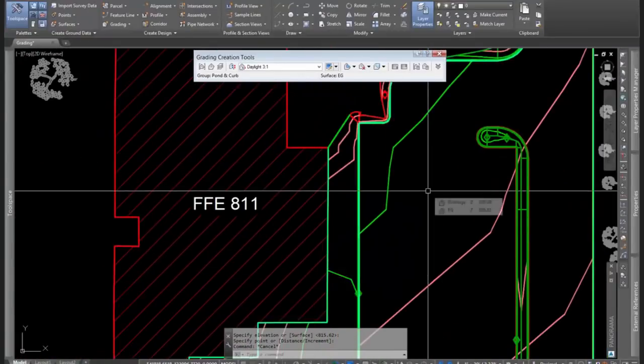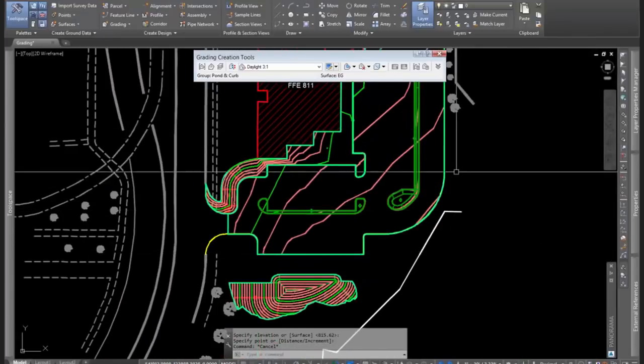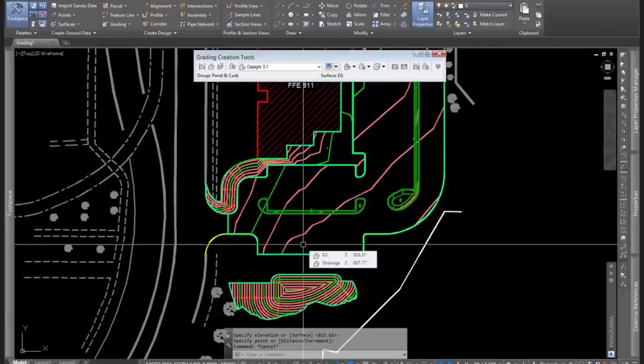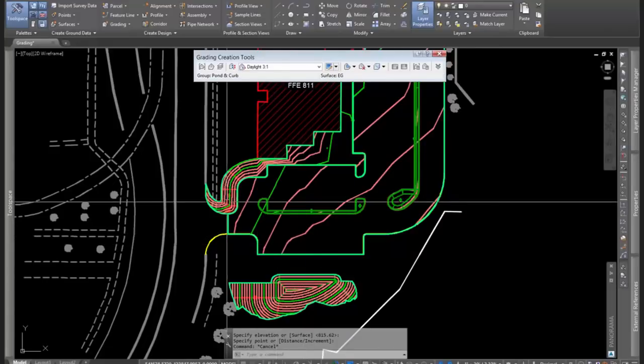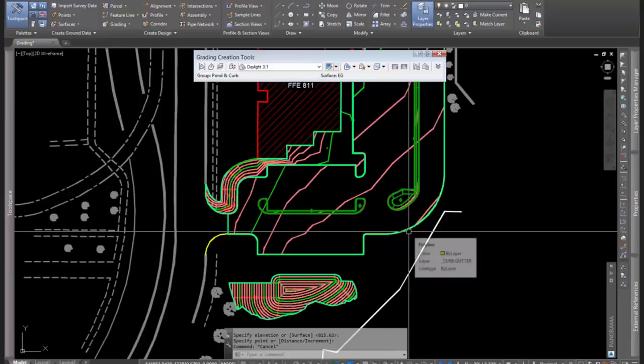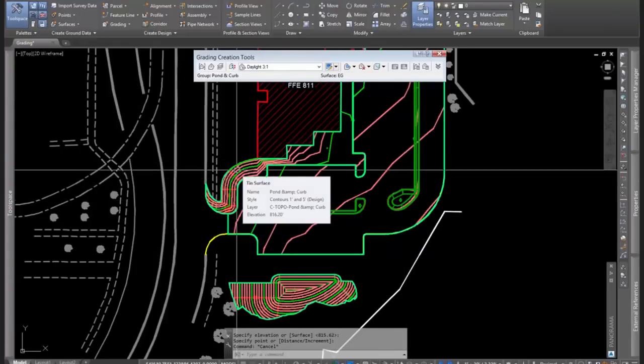So one final step here, and then I think we'll wrap it up for this webinar. The process on the back side here is going to be real similar, and I'll do it at the beginning of the next webinar, the part 2 of this, but it's going to be putting some curb in, some daylight gradings. We're going to add one other element to it, which is going to be to put a retaining wall on the back side of this. This will be much like adding a daylight to surface grading, but it'll just be a much steeper slope.